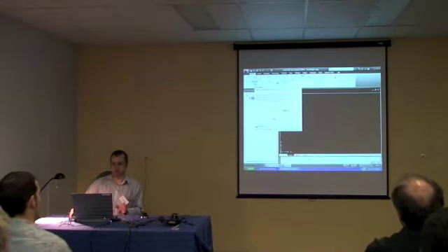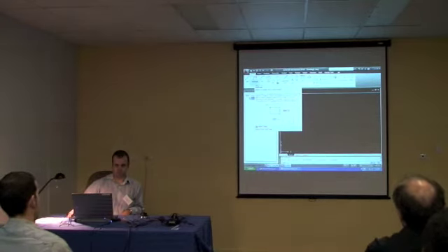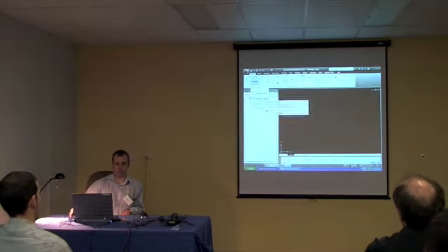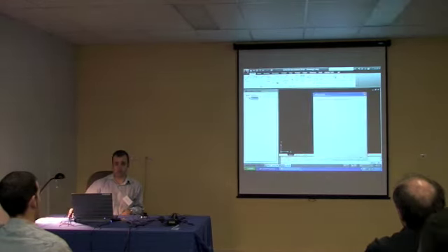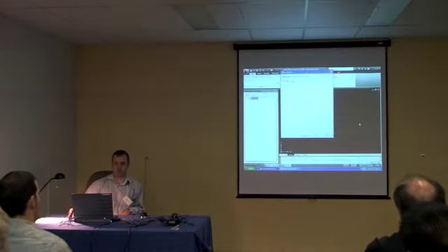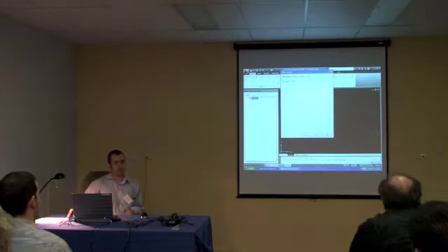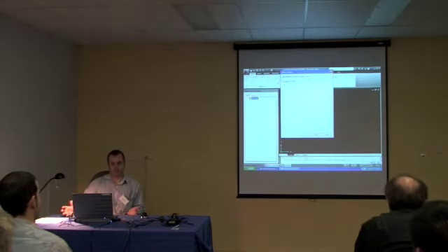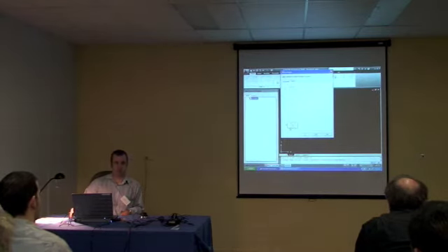Now, rectangles. Rectangles are pretty boring, right? AutoCAD Mechanical has various ways to generate a rectangle. It's not just two points. We have the base point, the height, the center, and a corner. There's a more option, which gives you a whole bunch of options on how to generate a rectangle. Or a square, which has equal sides. You can pick a point and a dimension, and it'll take that dimension and put it in.